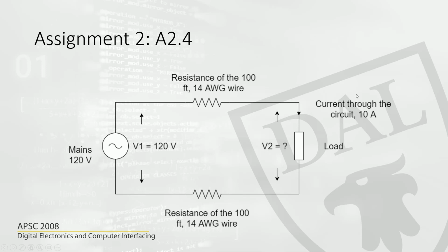As the distance goes up, from 5 feet to 10 feet, 15, 20, 30, you will see the conductor's diameter increasing. You will have bigger wires actually. That is because they had to take into consideration how much voltage will drop in the wire. So that is very important when you buy an extension cable.